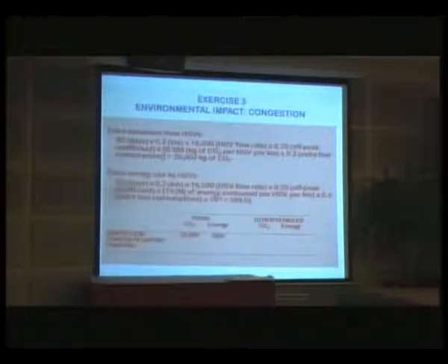In order to carry out the inspection, we're going to have some lane closures, and we've assumed it's going to be 0.2 kilometers. The traffic flow rate on the bridge is 80,000, of which 20% are heavy goods vehicles, and so that's where the 16,000 comes into it. We're assuming that we'll be able to carry out these inspections during off-peak hours, probably at weekends, and so there's an off-peak coefficient of 0.25 which has been introduced,